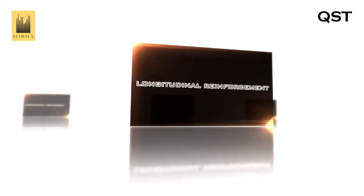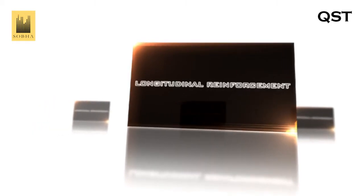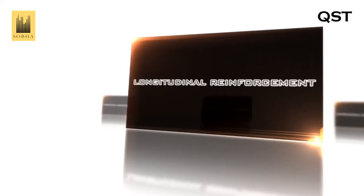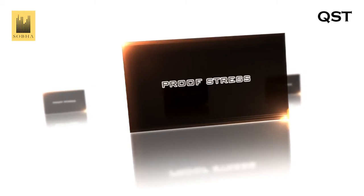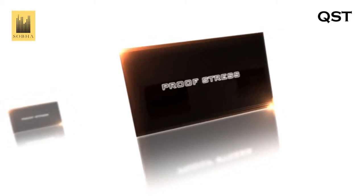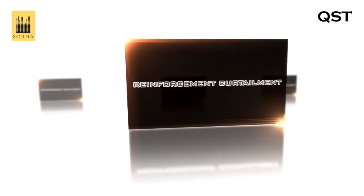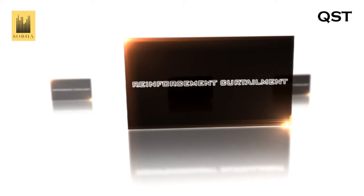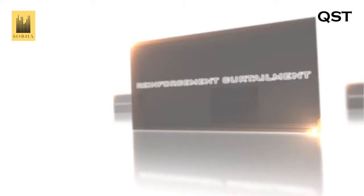Longitudinal reinforcement. The main reinforcement provided in an RCC member to take care of the bending moment is called as the longitudinal reinforcement. Proof stress. It is the minimum stress over a given area that can create a permanent deformation on it. Reinforcement curtailment. The steel reinforcement can be cut or stopped as it is no longer required to resist the flexure. It also makes the RCC member more economical.